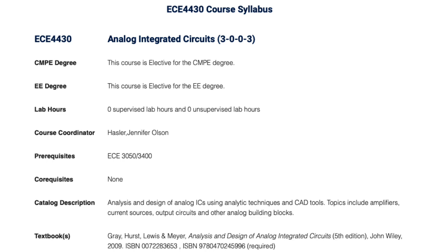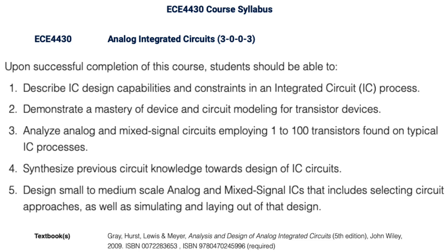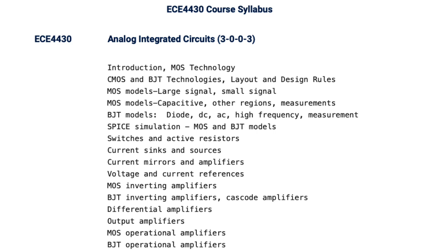Basically, the entire die on the chip defaults to one giant transistor unless you want to split it up and do otherwise, which of course you want to do. But basically, the transistors are pretty cheap on a chip, so you might as well use them. And using matched sets of transistors, where you don't know the characteristic of any one transistor, but you know that they're going to have similar characteristics, is a thing that you can exploit in your design.